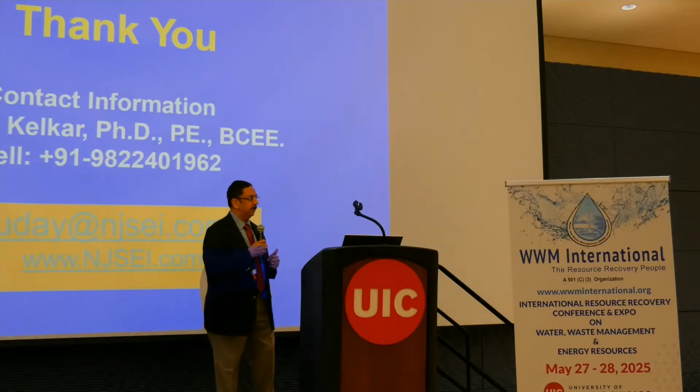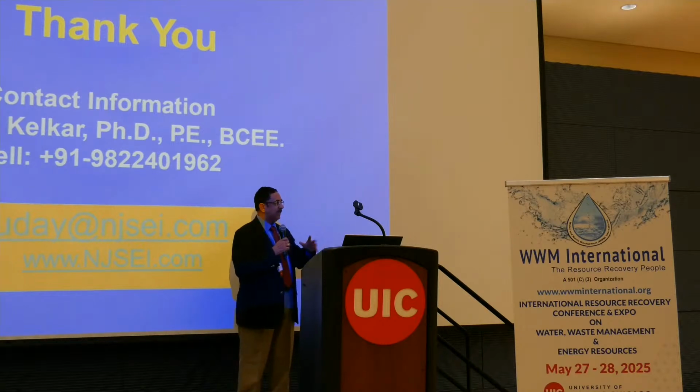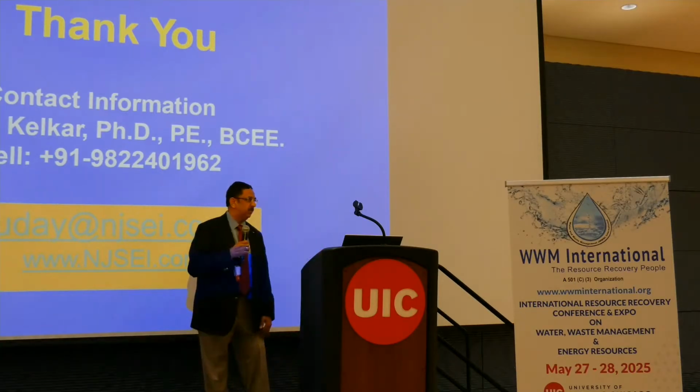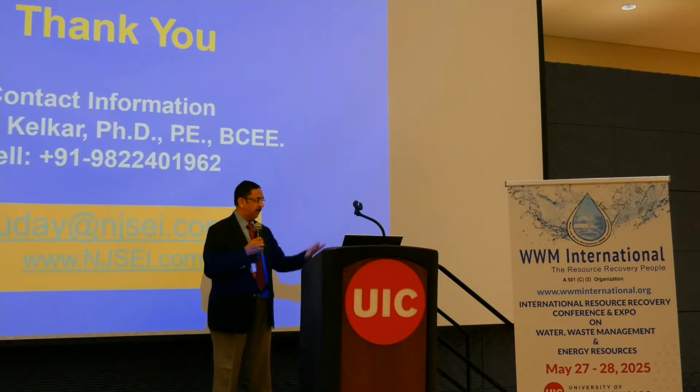In terms of the carbon, when you are performing anaerobic digestion, you are converting carbon to methane, biogas. So keeping the carbon, avoiding anaerobic digestion, could be a better value proposition, save cost. Did you guys look at that? We looked at combinations, and in Indian scenarios, the volatile content is not as high as you see in Western countries. Typical VOCs are 35 to 40%. So the city can either choose, if they don't have digesters now and they don't want to build them, they can use the sludge straight and save on the carbon.